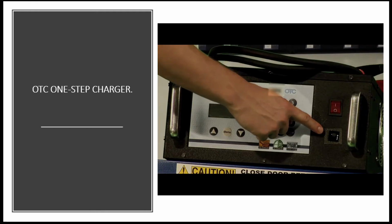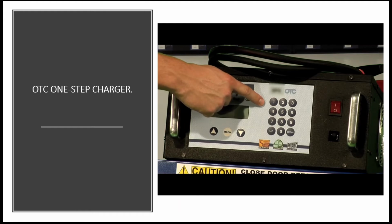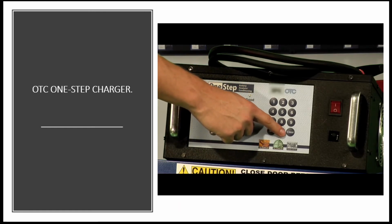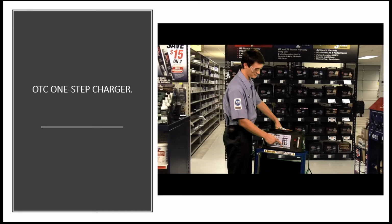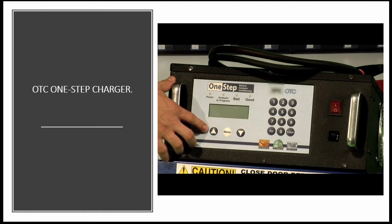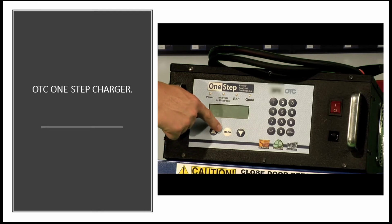Use the number keys to enter numeric information. Press the clear key to remove information entered onto the display or to stop the battery testing procedure. Press the go key to start a test program. Press the up-down keys to scroll up or down to the next line on the display window or go to the next screen. Press the menu key to select the main menu.